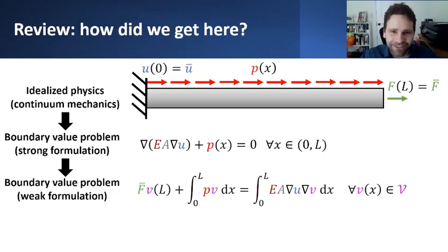They still themselves have to be continuous functions for the displacement field in order to satisfy the fundamental requirements of compatibility. But their derivatives need not be everywhere defined. Now, that was a nice additional thing that admitted a new class of functions that had possibly not well-defined derivatives everywhere, and we'll take advantage of that fact momentarily.